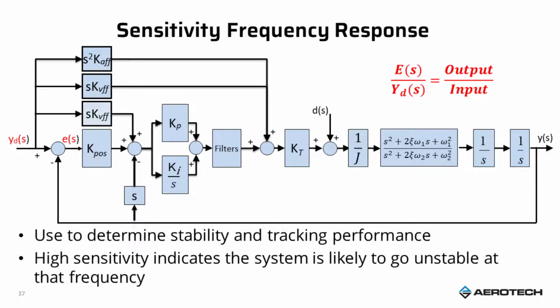The last frequency response to discuss is the sensitivity response. This is the transfer function from the output error, the servo error of the system, to the input command, YD of S. And this is often helpful when trying to look at the stability of the system and look at instability points that might not be obvious in the standard loop transmission.